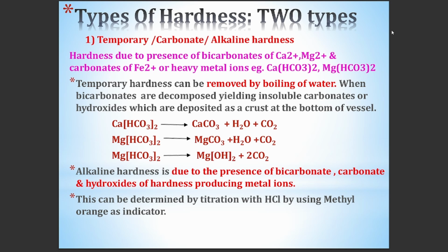Similarly, magnesium bicarbonate forms magnesium carbonate, and then magnesium hydroxide, which is a precipitate. These salts get precipitated at the bottom of the vessel, and we can just filter it, and this water becomes free from the temporary hardness causing salts.